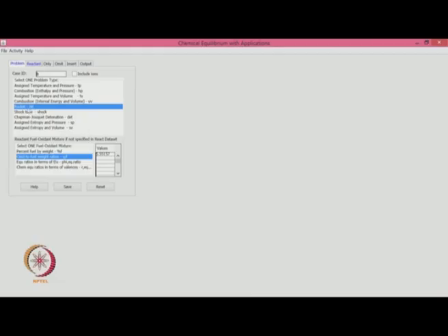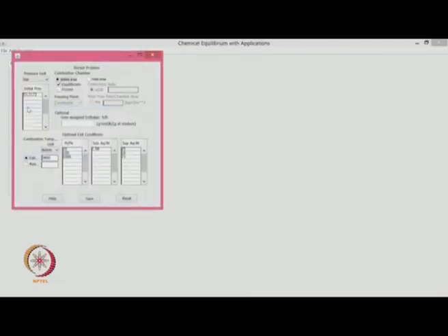Okay. Now here if you look at this, this is an example problem. The initial pressure is set as 53. We can change that to something like 100 bar. Okay. You can input at one time many more pressures, 150 bar and 200 bar. Okay. You can also have different units in which these can be expressed. We will click both equilibrium and frozen,